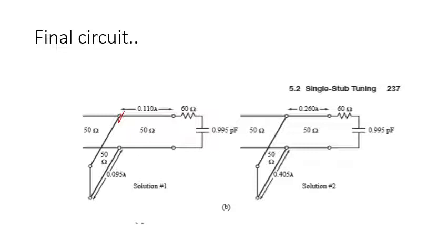The important point over here is that a 50 ohm matching network is here. The D has to be marked and L has to be marked. Only D and L. The rest you can ignore. Please ignore it. That is computer generated using some CAD software they have solved it. You need not do all these things. You can just mark this 50 ohms, the D and the L. With this your design gets over. So I have given you one more